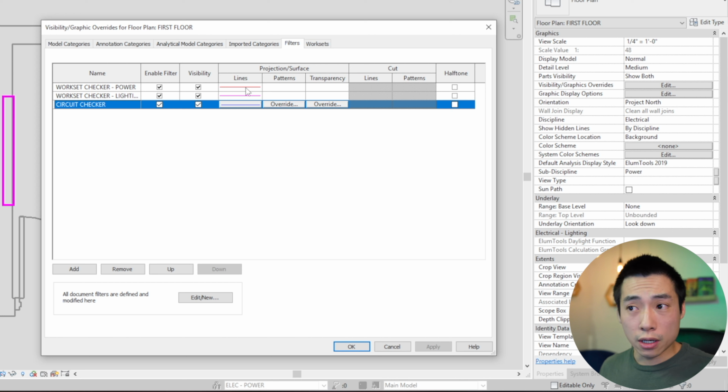So yeah, you can have all these colors, and then you don't have to enable these all the time. So that's the thing I want to make sure. You don't want to keep these on your plot view. Put this on your working view or something, because if you plot in color, as some companies do, this will actually get sent out the door that way.